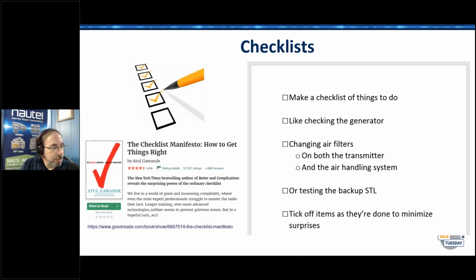A good point there. Mike Fertini says install hardware cloth over the vents outside of the HVAC units to keep mice and snakes from entering. Now, I'm going to qualify that a little, because your average 1/4-inch hardware cloth won't stop a mouse. A mouse can get through a 1/4-inch hole. Having said that, it will stop a lot of the other critters. So definitely something like that is a good idea.